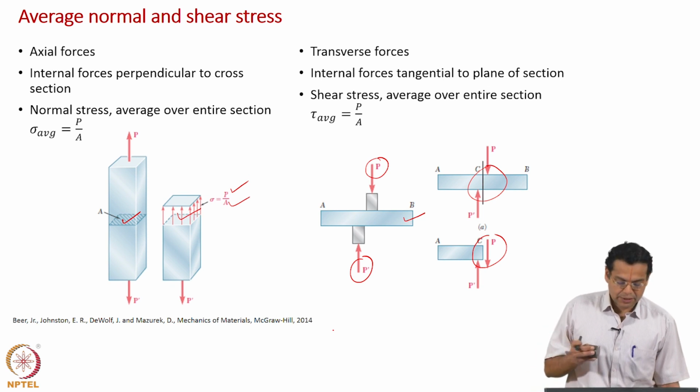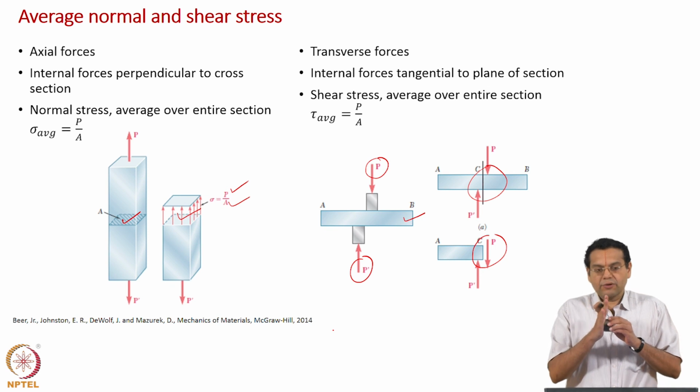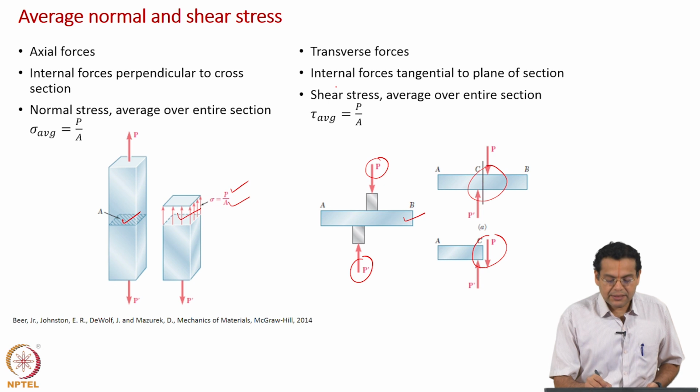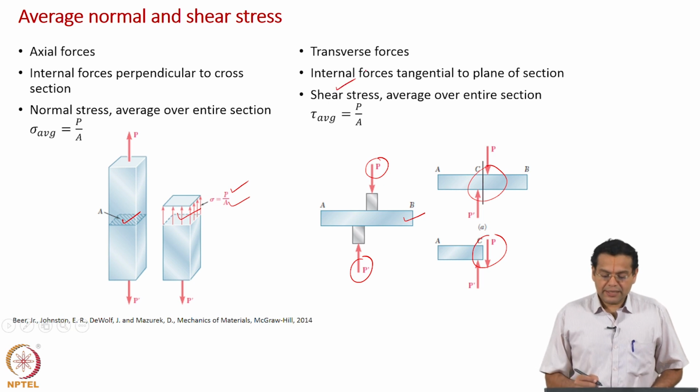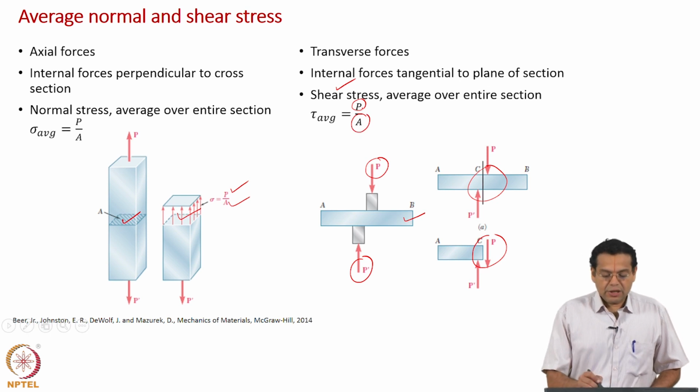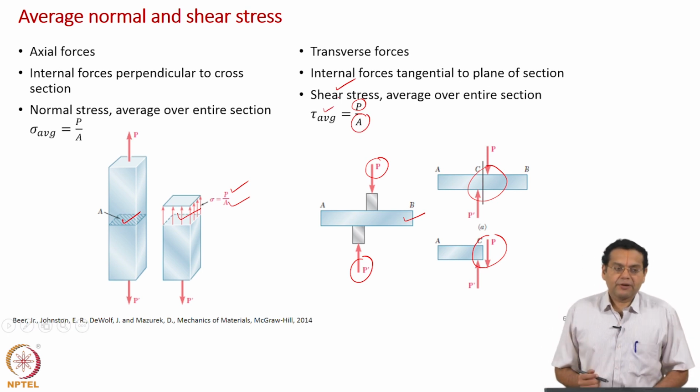Okay. So that force acts tangential to the surface, and hence it is named shear stress. So how do you once again evaluate that? You take the magnitude of the resultant force, if you denote it as P, and then area, now area becomes the tangential area, and if you divide you get the average shear stress.